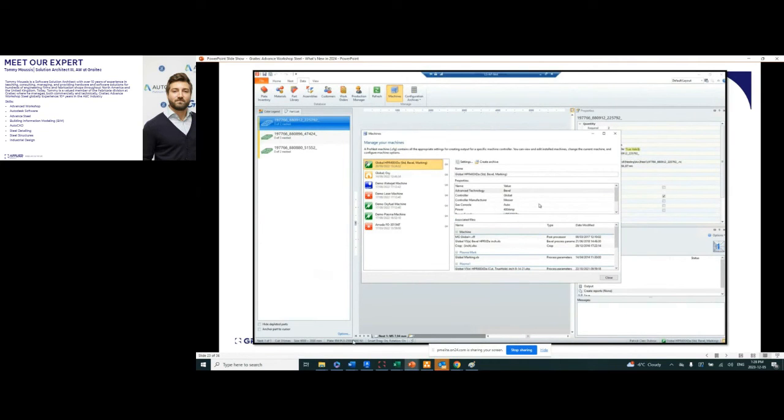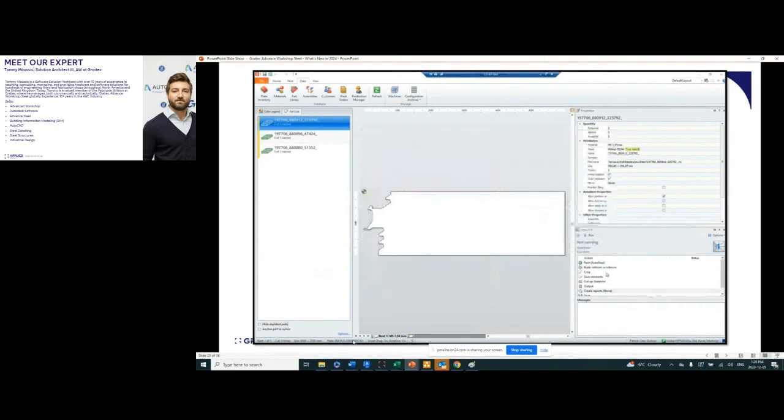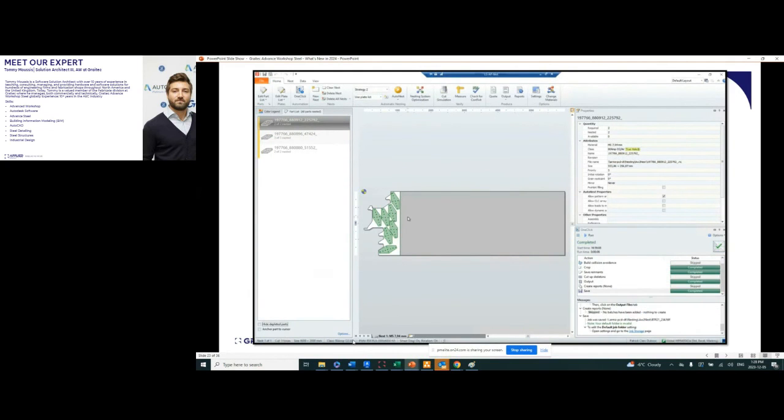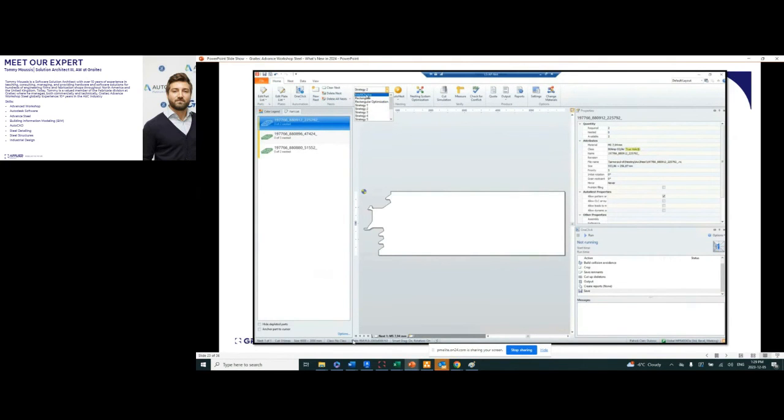Ideally, you'd want to be able to see the remnant's geometry if you were to nest plates against that remnant. With that said, we can leverage both new plates and remnants depending on which version of ProNest you have. Once that's done, here we'll see the plates nested against the remnant. And then that can be exported, saved, and then expedited to the machine to be processed.